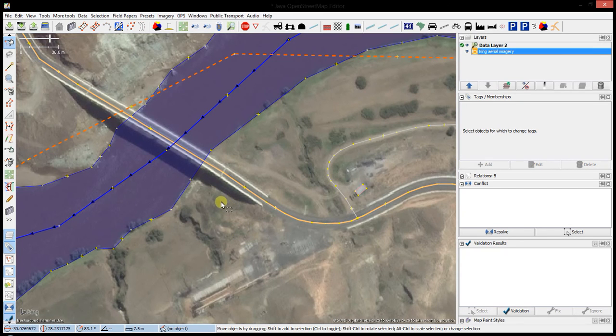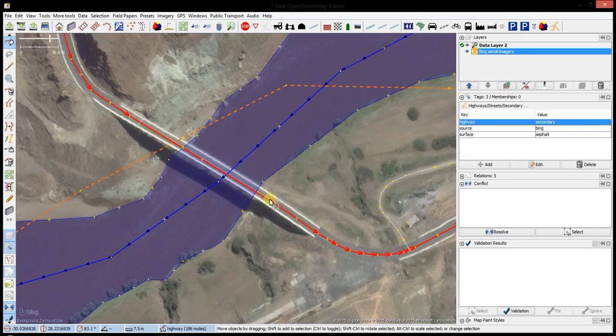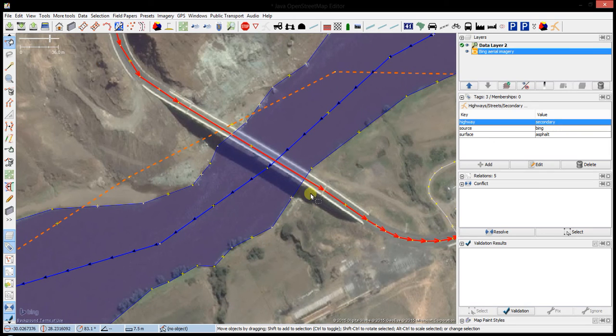So next we're going to look at where you have a bridge over a water feature. So in this case I have a river here. So what you do is essentially the exact same thing. You're going to split, but this time you're splitting the road because your road is the feature that has changed. Your river is still just flowing normally. It hasn't been diverted in any way to bypass the road. So in this case your road has been changed to avoid the river.